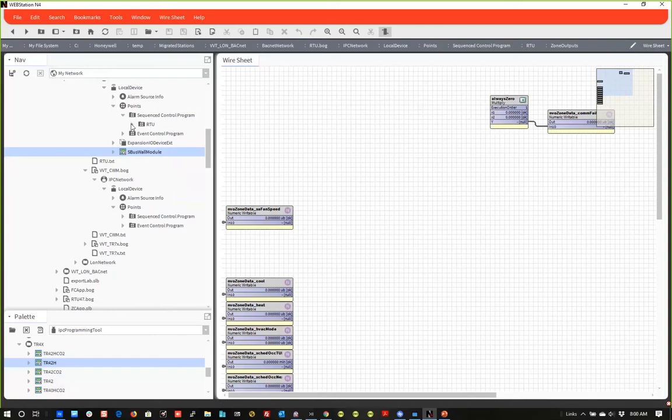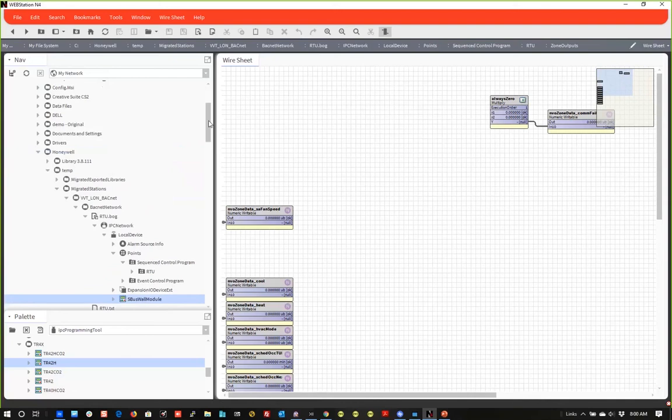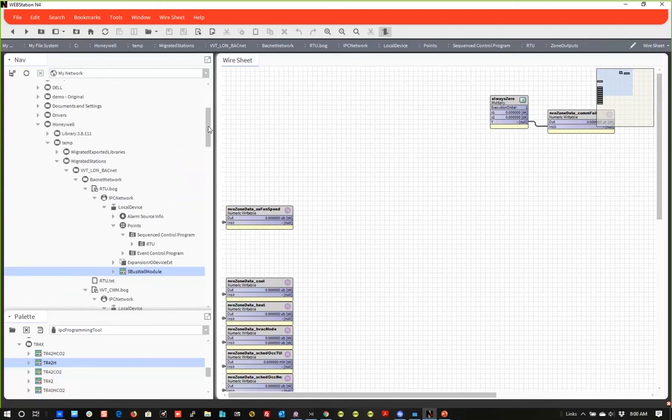And what I've been told is some of the enhancements to this as well, all the balancing routines will be done with tagging. So by using a certain set of tags on various parts and pieces of the VAV boxes as well as the air handlers that serve it, you would be able to, in the balancing routine, speed up fans, slow down fans, things of that nature that you would like to do within the air handler to enhance the balancing procedure. You would be able to control the air handler as well from the CIPer 30 balancing routine.